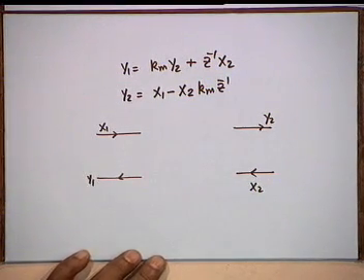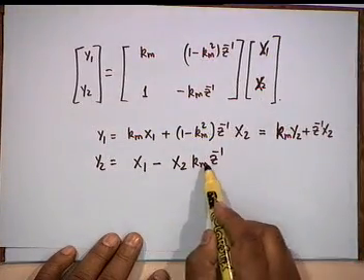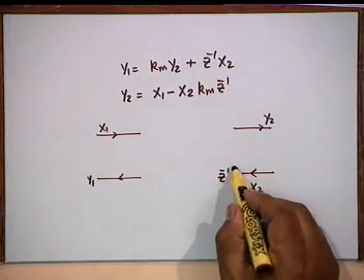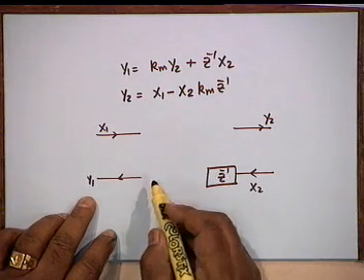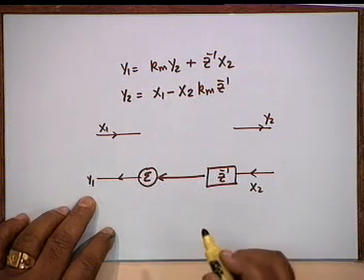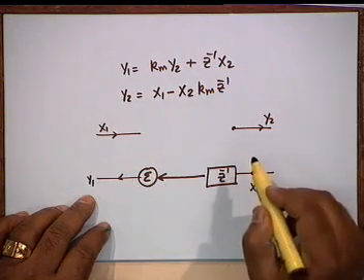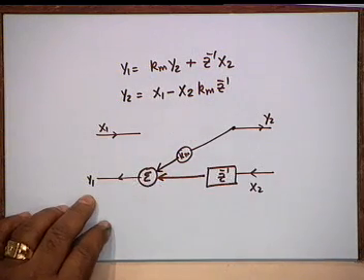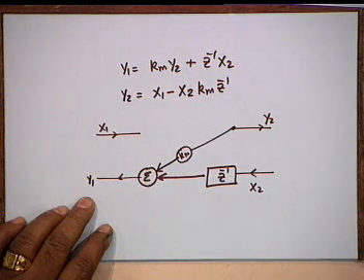You notice that in both of them we require Z inverse X2. Okay. So X2 we delay by one sample, X2 we use a Z inverse. And then to construct Y1 we require Z inverse X2, we require this input and Km Y2. In other words, we require from Y2, we will see how to construct Y2 later, this multiplied by Km. Okay. Y1 is Km Y2 plus Z inverse X2. So we have constructed this.